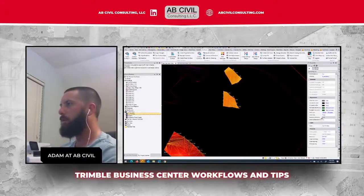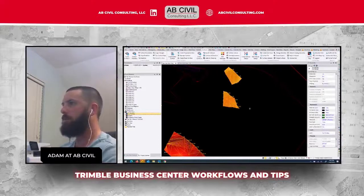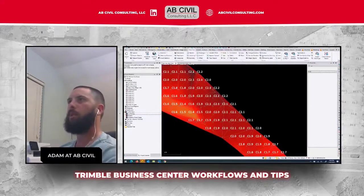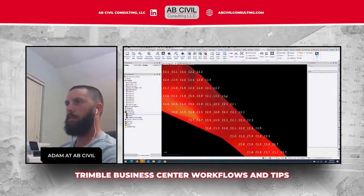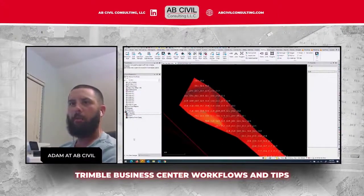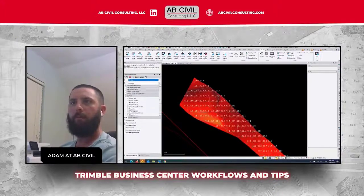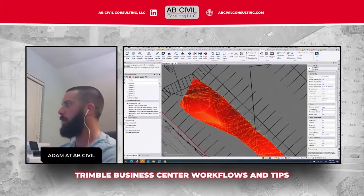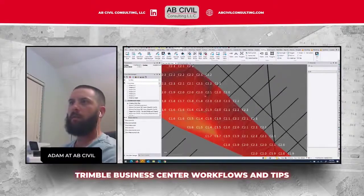So I'm going to actually change the decimal precision on this. If you highlight the cut fill surface, decimal precision, I'm going to go to 0.1 so that the text isn't so bad. And then it's actually bold text, which sometimes doesn't work real well, so I'm going to go change that quick. Alright. So now you can see this is a cut fill map. Maybe I can put on one of my PDF background images. By default, they're not transparent at all. Just make it 20. So here it is.